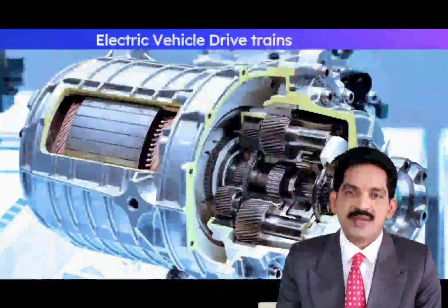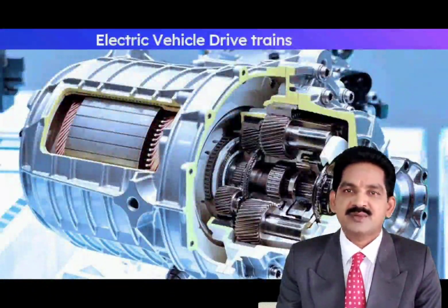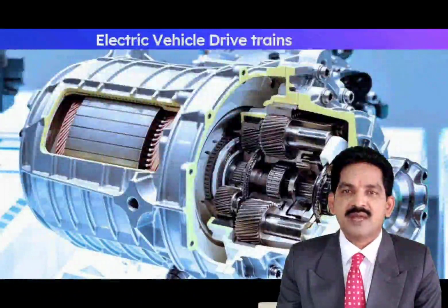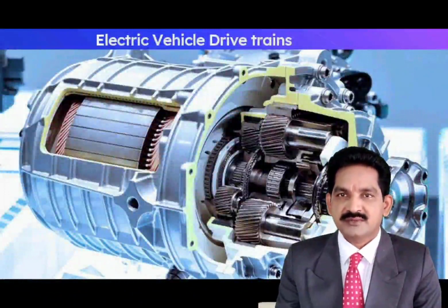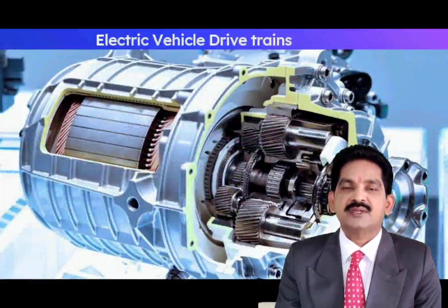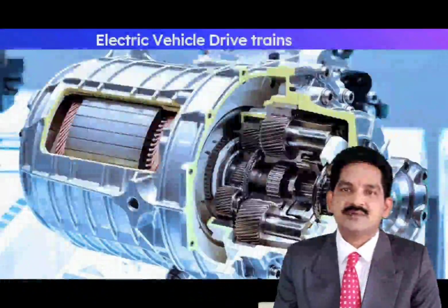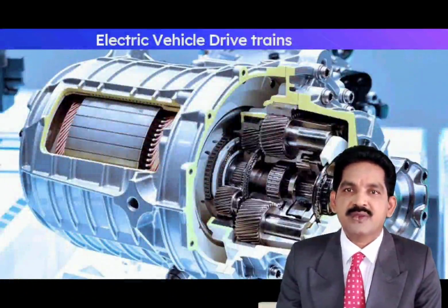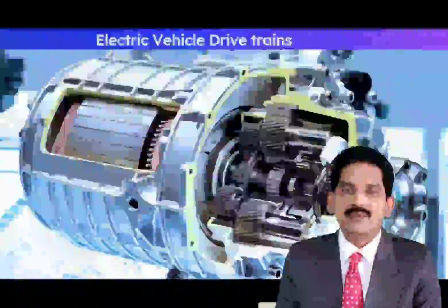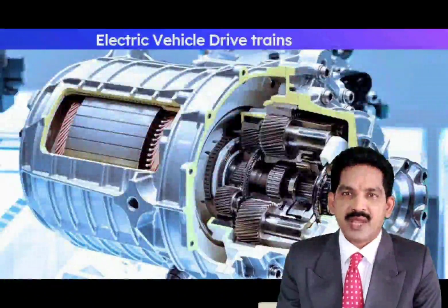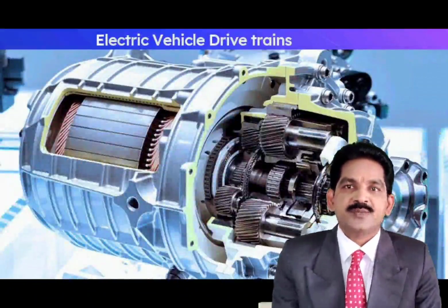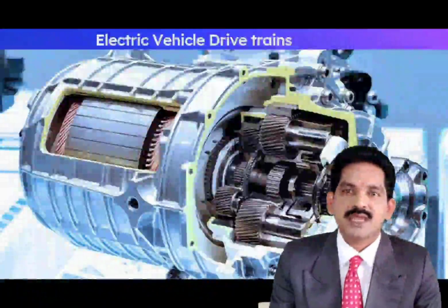Often, electric motors, power electronics and drivetrain share a single housing, reducing the overall number of components in the powertrain and lowering the overall weight of the system. In battery electric vehicles, this integrated unit may directly power a combined electric axle drive. In hybrid electric vehicles, various transmission configurations are possible depending on how the manufacturers intended the electric motor and combustion engine to interact with each other.